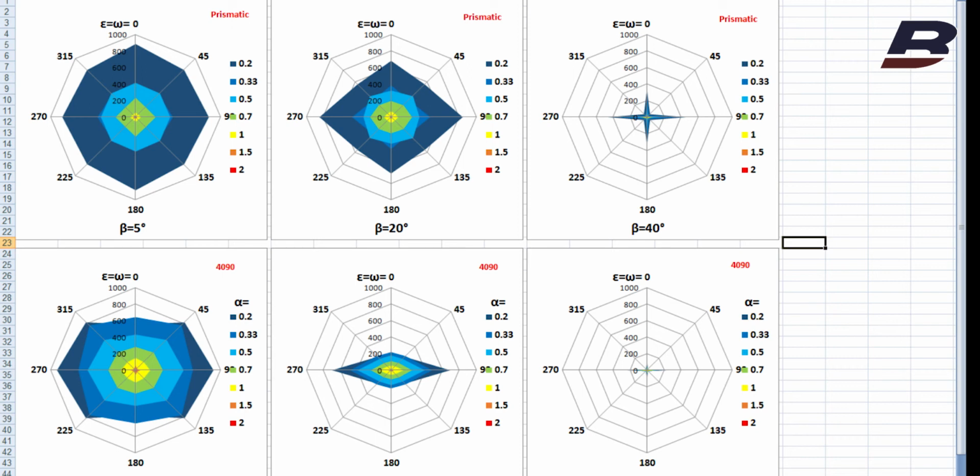However, starting from 20 and even 15 degrees entrance angle, the retroreflection gets lower and lower, and for 40 degrees, for example, entrance angle, the retroreflection of DigiCube is way lower than the retroreflection of traditional cube corner prisms. You can do these measurements yourself. No need to trust only my measurements.